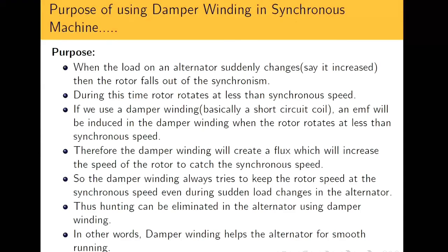So this additional EMF developed in the damper winding will create a flux, which will increase the speed of the rotor to catch the synchronous speed. It will increase the speed of the rotor to catch the synchronous speed.